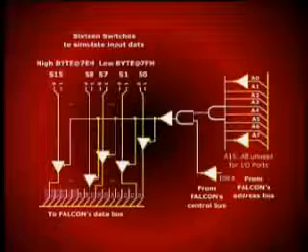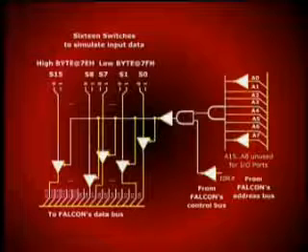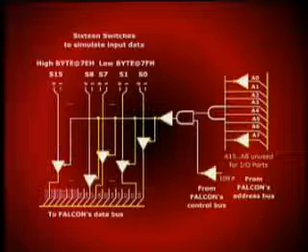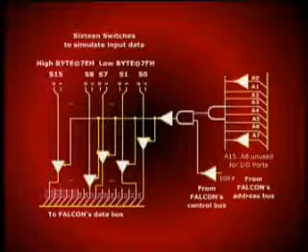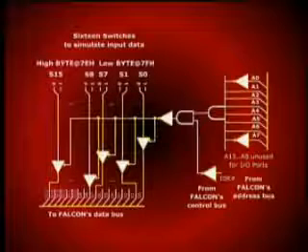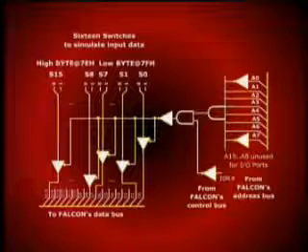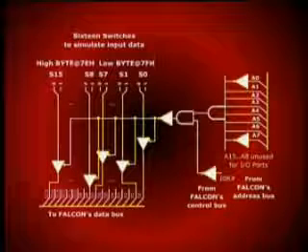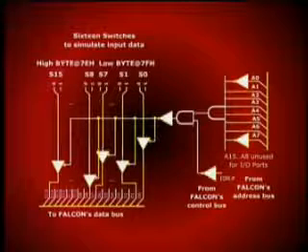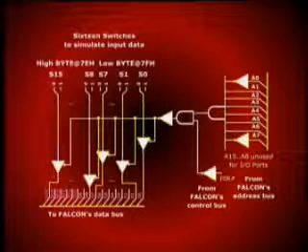The address line A0 is an input to the next two AND gates. One AND gate utilizes it in inverted form and would map the corresponding address as 7E. The output of this AND gate through an inverter enables the top byte, the most significant byte, and therefore enables the 8 tri-state buffers corresponding to D8 up to D15.